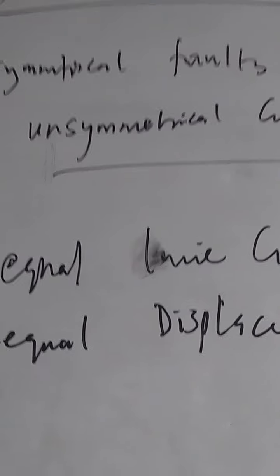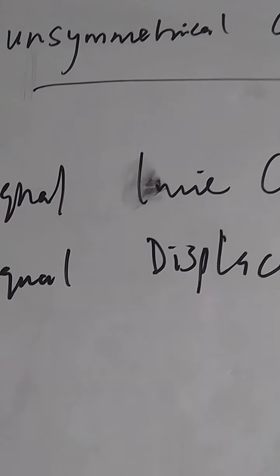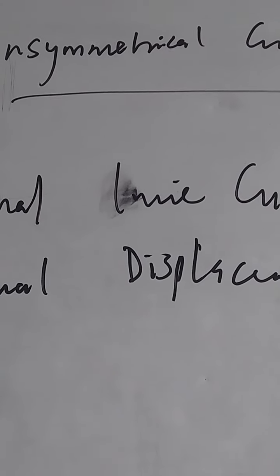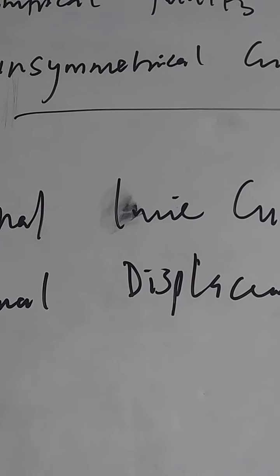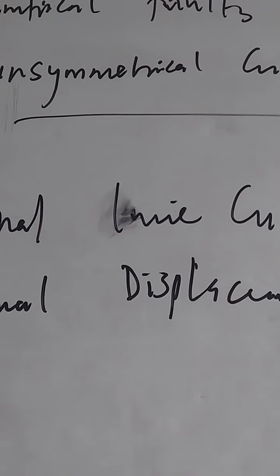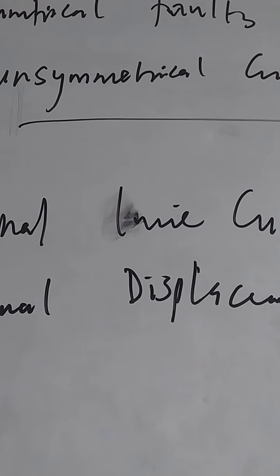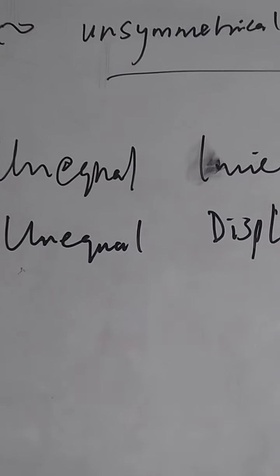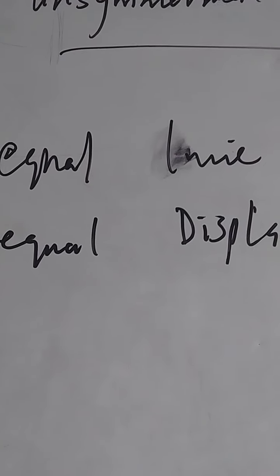That means that the unsymmetrical fault we're talking about only applies to the fault itself and the resulting line current. The impedance, the constant, and the voltages, the source voltages, those ones are always symmetrical through the main elements. Now, let's look at a proper analysis of unbalanced condition in a three-phase network.